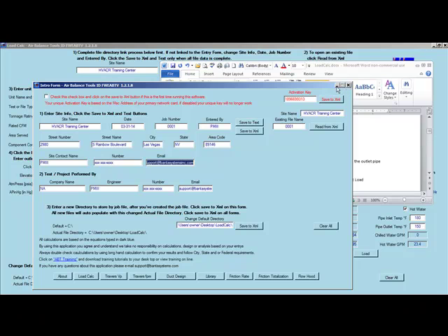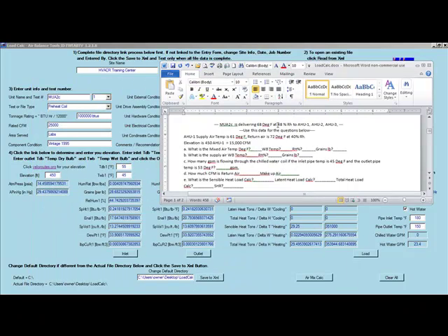So let's continue on. So the next test, we're saying that MUA2C is delivering 60 degree at 48 RH to air handlers 1, 2, and 3. Air handler 1 supplier temperature 61 degrees, and the return air is 72 at 40% RH. Our elevation is the same, 450. And these machines deliver 15,000 CFM.